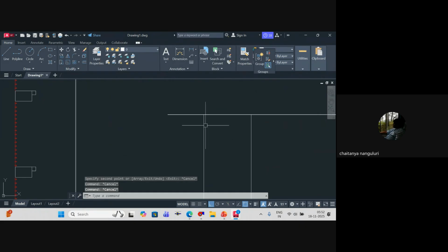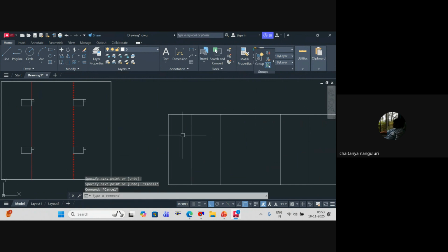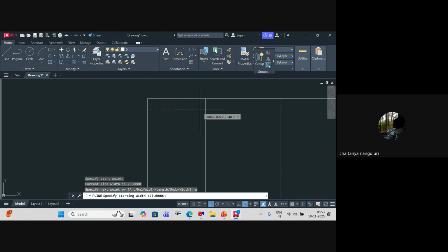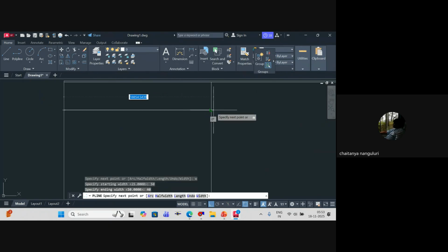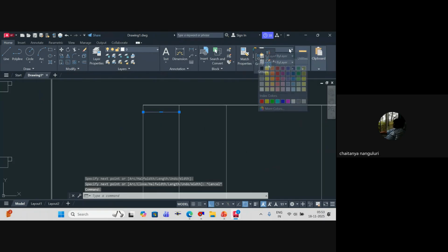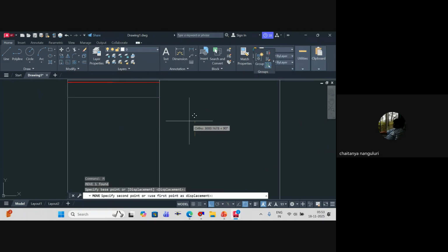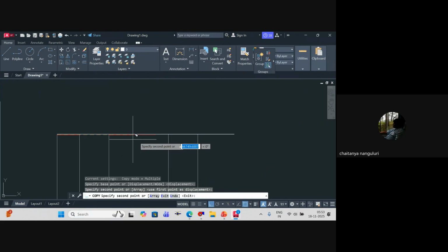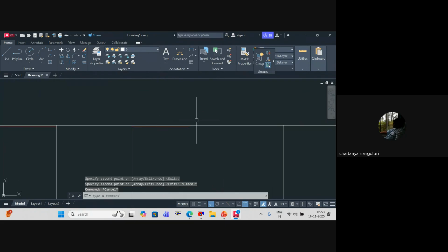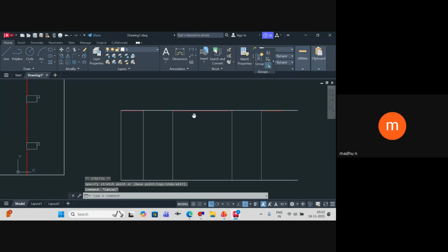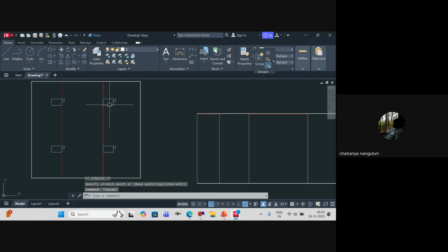So already this wall will act like a fire barrier. So my nozzles will be from your external wall to here only. I'll have my nozzles only in this direction. Again, I'm having it at this location because the wall itself will act like a fire barrier for me. Understand? Am I clear? Yes. So we try to utilize those structures so that the number of nozzles or water demand will reduce. I'm clear.